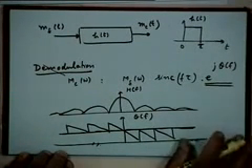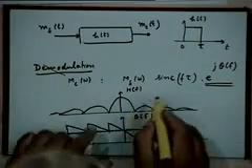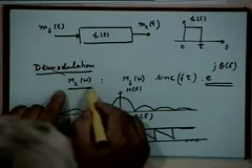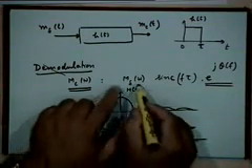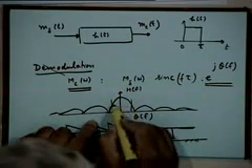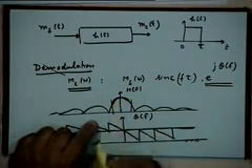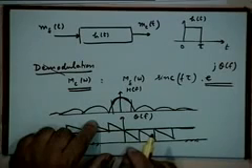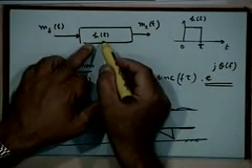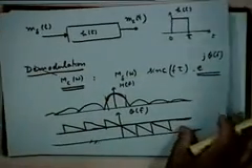Okay. So, the important point is this, that the spectrum of the received signal is not just the message spectrum that you are looking for, it is getting modified by this shape here, right. Some kind of filtering is being done, right, by this filter h(t). So, you have to equalize for that, so that it is equivalent to coming back to your impulse sampling.